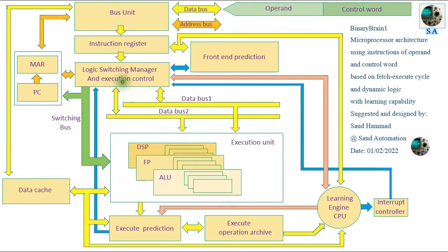And when a new instruction is loaded, and if the same control word is requested, then it will just allow the operand and data to directly pass for execution, because the right logic mode is already set and connected. Therefore, just go ahead and process the data, and at the same time discard the currently loaded instruction and fetch the next instruction immediately.